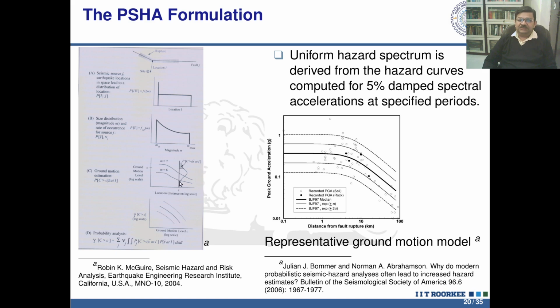Now, what is this ground motion prediction equation? Just to explain this idea, these are the ground motions. For example, this is peak ground acceleration. So we collect a database, the acceleration database that I showed, a collection of time histories of different earthquakes. So we just plot magnitude against peak ground acceleration in this range. Naturally, this is a random event, so we see a lot of scatter here, right?